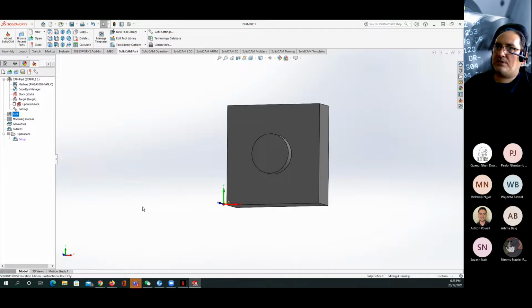I have the tool now. Other thing we can do is, for example, we can decide what the fixture is. Usually for this operation, you need to sketch your fixture. You can make the CAD model for your fixture, and then you can import it to the Solidwork through the fixture thing. Now I will go to the setup directly. I have a cutting tool now. Everything else has been identified.